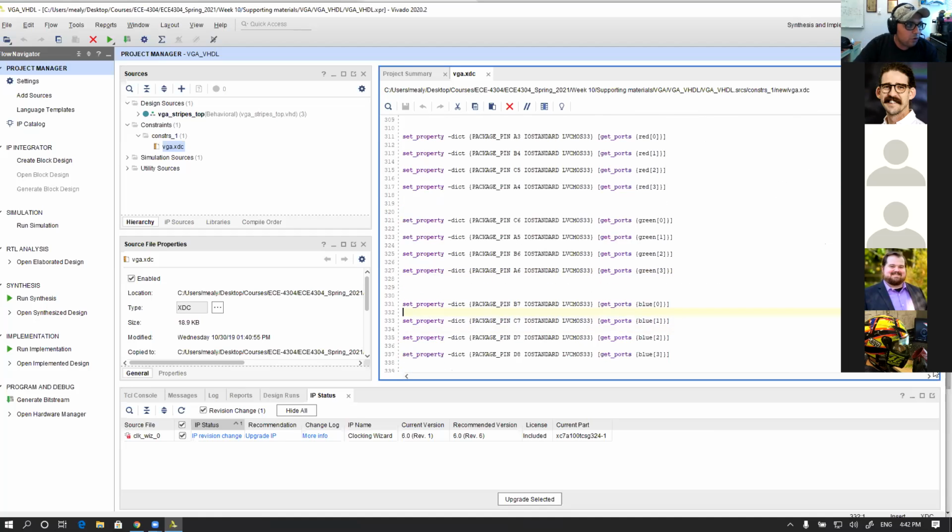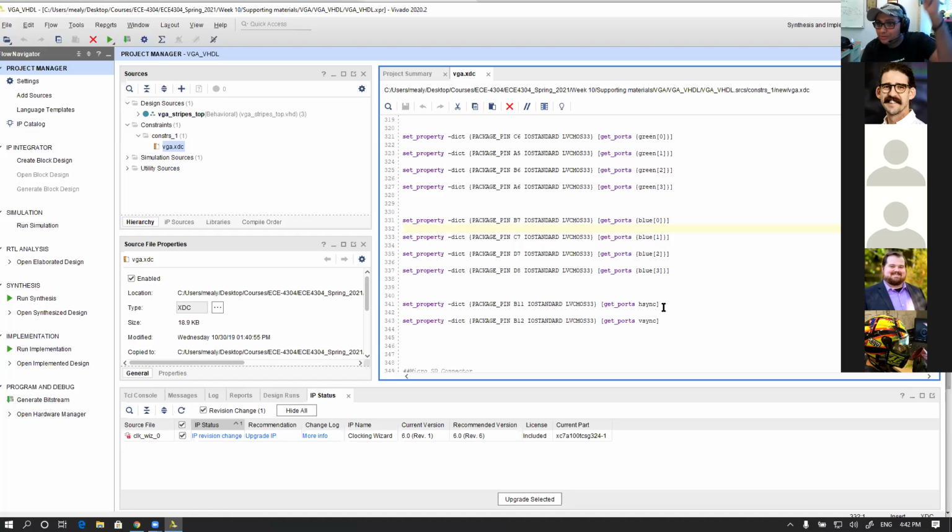Are we done? No, we are not done. Still, we need 2 signals inside the VGA as an analog. One synchronizes the horizontal, one synchronizes the vertical. We need to be sure those are on, off, on, off, so we can send a signal to the whole sheet on the screen saying that I'm ready to present anything I want to present. That's the physical connection to the analog side. So everybody is aware now, right? We have 3 different colors and 2 signals, one for horizontal sync and one for vertical sync. So far, so good.